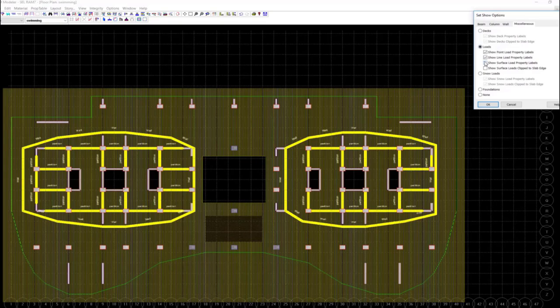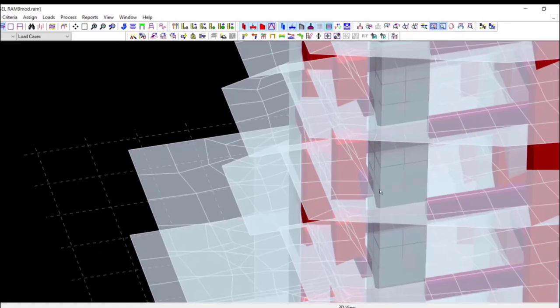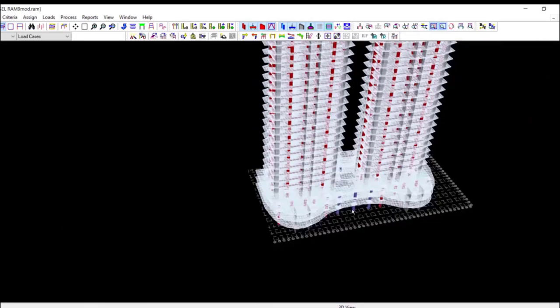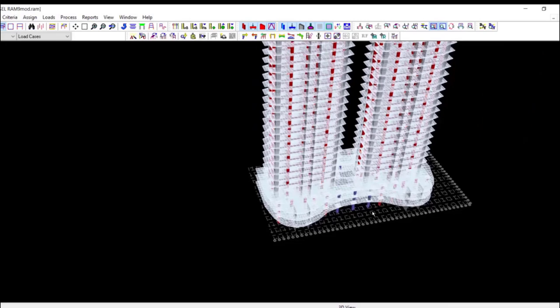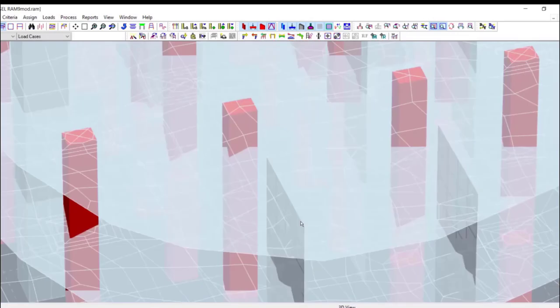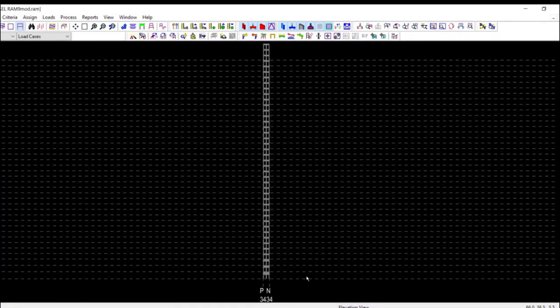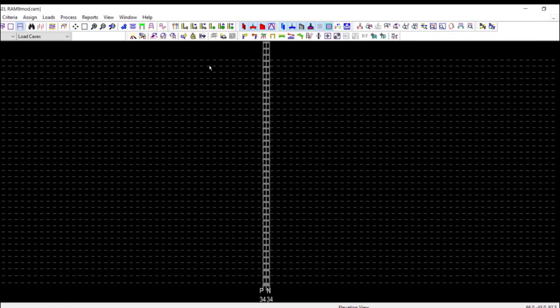Now let's take a closer look at the meshed slab and the shear wall. Please note that RAM Structural System models the structure as a physical model, and hence the analytical model, like the meshing of the plates, is automatically generated by the program maintaining the proper aspect ratio, considering all the control points. See here how nicely the internal columns are considered as the control points. One can also change the default mesh density.